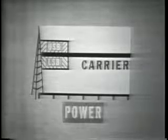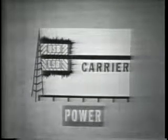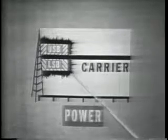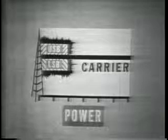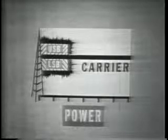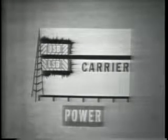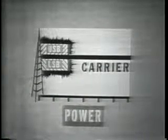And also, since we have two sidebands, the required receiver bandwidth allows in more atmospheric noise at the received end. Noise, of course, is proportional to bandwidth. Thus, the wider bandwidth raises the noise level of the signal. If the signal is very weak, it may be lost in the noise and thus be totally unusable.